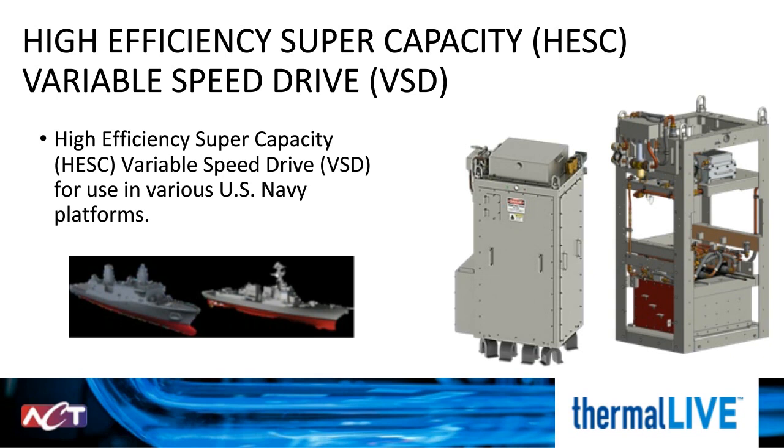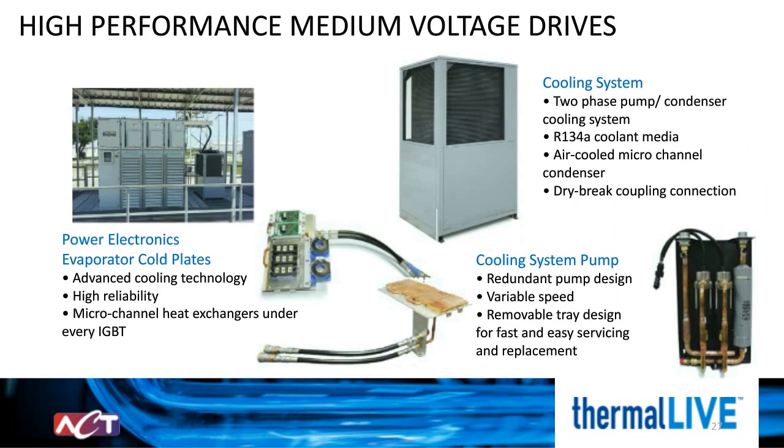The second unit was designed for high-performance, medium-voltage drives. This design includes a power electronics-specific evaporator cold plate that is highly reliable and has a microchannel heat exchanger under every IGBT placement zone. The cooling system uses a redundant pump design with variable speed.